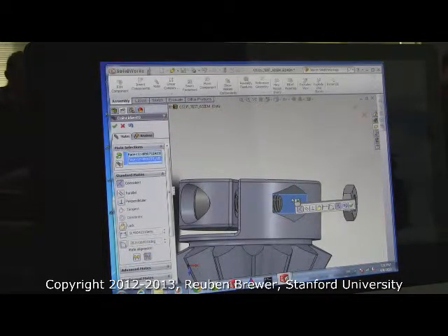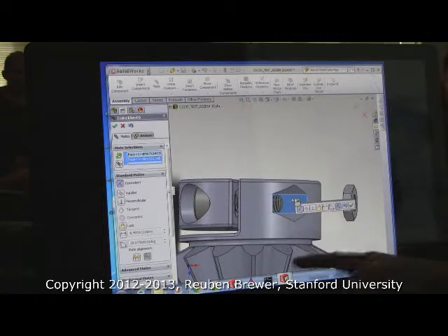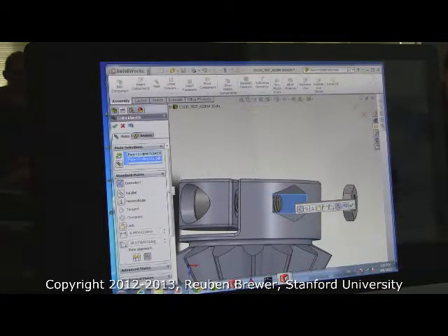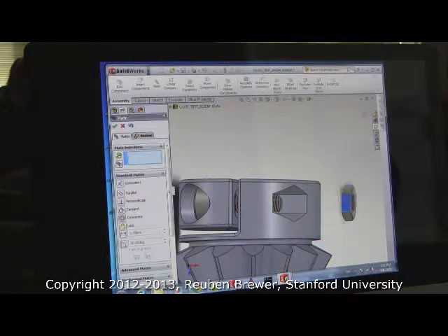Basically, depending on the surface, our 3D printer will add 2 to 4 thousandths on top of what we wanted, which means sometimes if we want to press fit, we have to adjust it so it's not perfect. So this hex hole might have to be a little bigger or a little smaller. If we do coincident, it won't work if they're not exactly on top of each other. If we press parallel, they'll be parallel like we want, but it won't be mathematically over-constrained. So press the green check mark, and now drag it around.